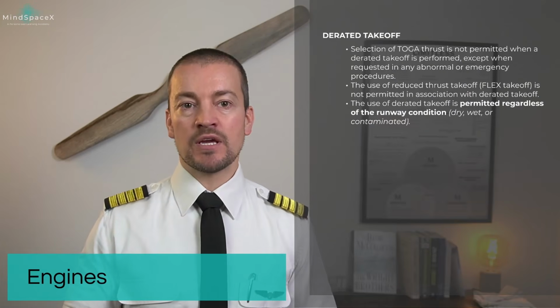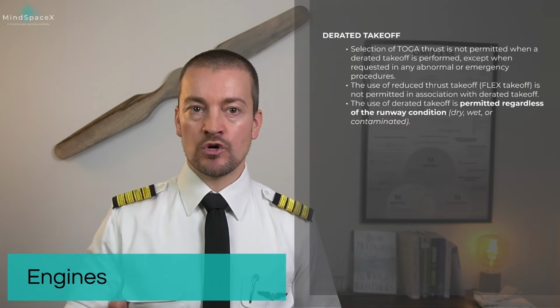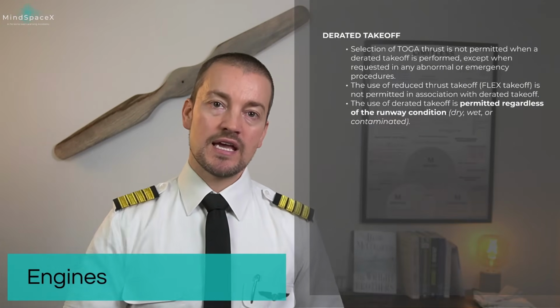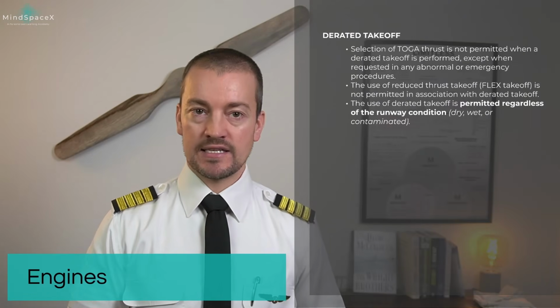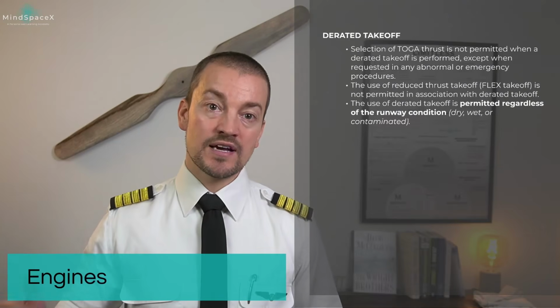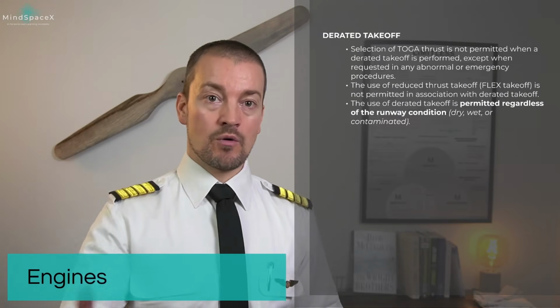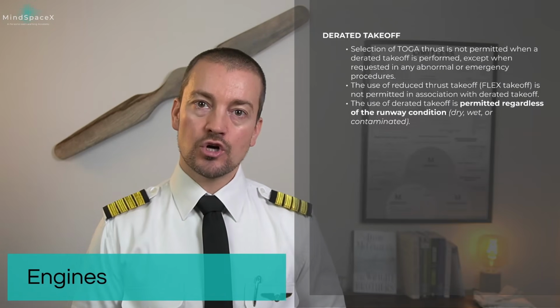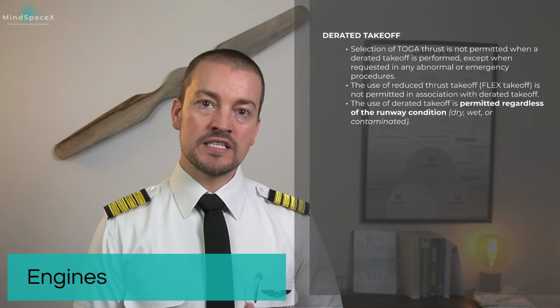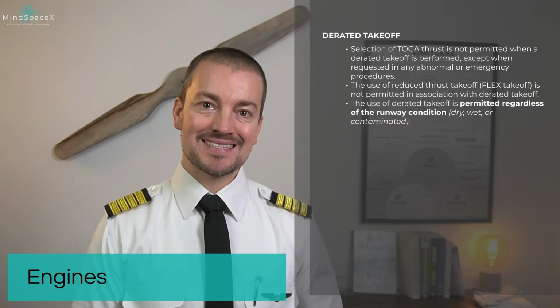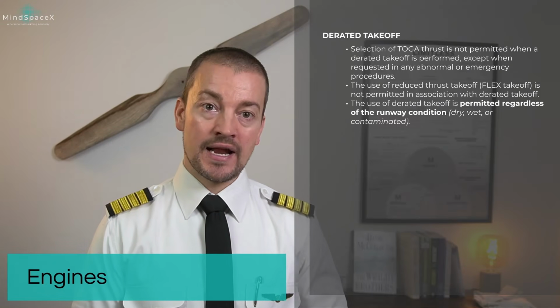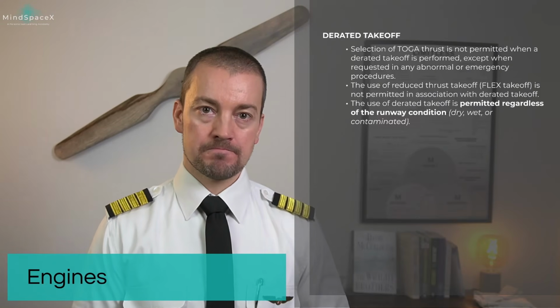Another way of saving performance for takeoff, if you don't need full power for takeoff, is doing what's called a derated takeoff. It does not optimize the same way that flexible temperature takeoffs do, but it is still better than performing a TOGA power takeoff. Selection of TOGA thrust is not permitted when a derated takeoff is performed, except when requested by an abnormal or emergency procedure.